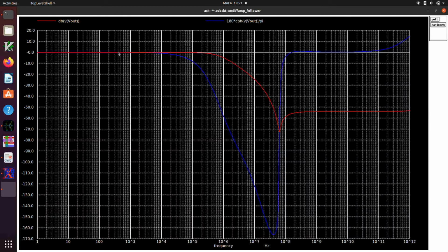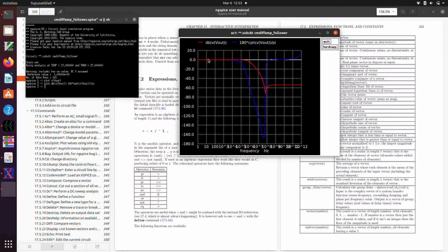And you can see the phase is in phase up here, 0 degrees, and then we start to see the phase maybe an order of magnitude in frequency below where we start to see the shift in gain, and then it shifts down, and then very abruptly we get 180 degrees of phase contribution from those zeros. Okay, so that's the Bode plot.